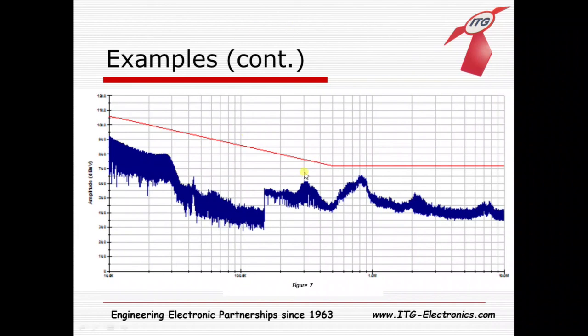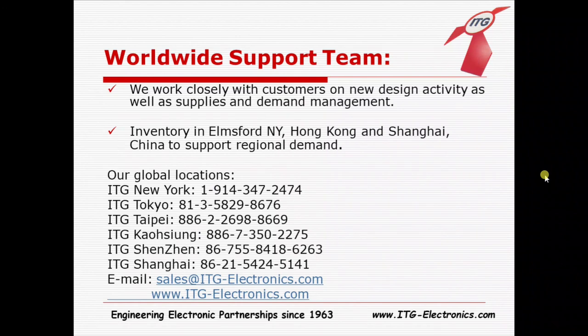But as you can see, this section right here in the middle is what was zoomed in. That dropped that well below the line now. We have a comfortable, easily 5 dB margin there, and everything is very, very much in compliance, and this would be a happy result for anyone in this situation.